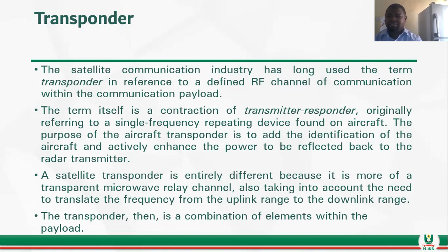A satellite transponder is entirely different because it is more of a transparent microwave relay channel, also taking into account the need to translate the frequency from the uplink range to the downlink range. Now, the transponder then is a combination of elements within the payload.